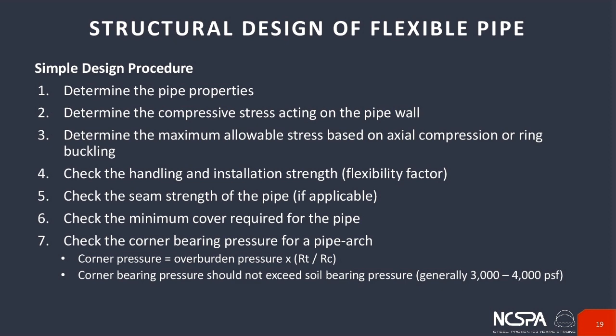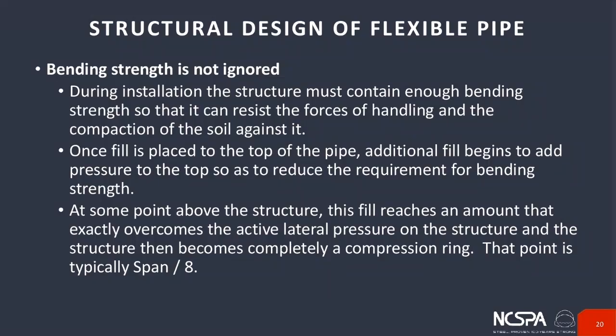So why is this important for today's discussion? Primarily because these structural design concepts are also applied during the installation process. As we said before, the pipe is completely backfilled and properly supported by the soil envelope. The pipe must have adequate bending strength to resist the shape distortion during handling and installation.